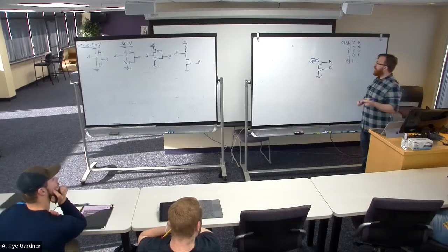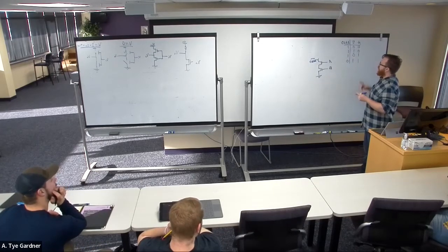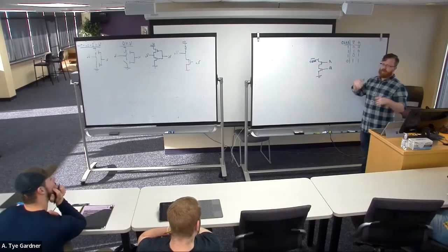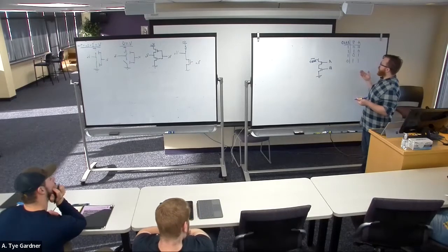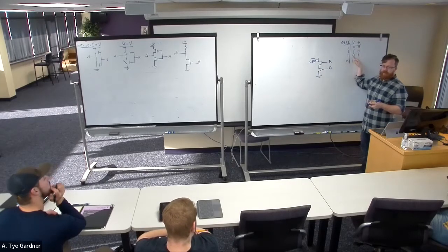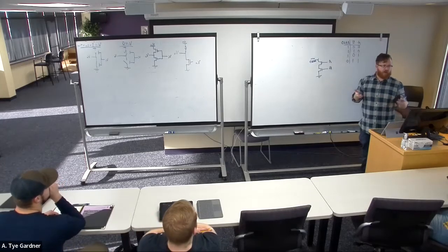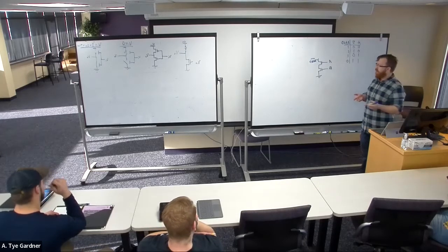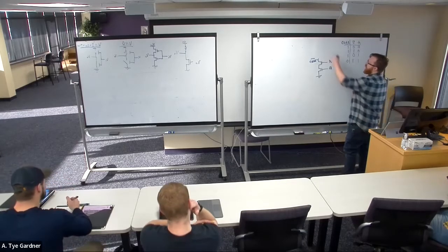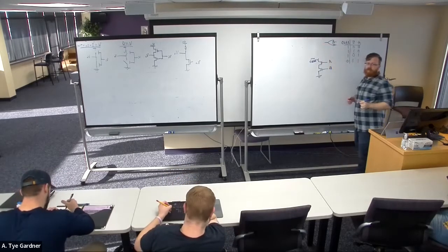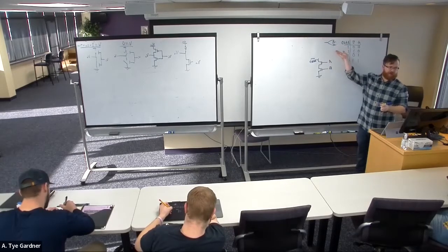Now I need to look at it and say, what happens if, or rather, let's do the other way. How do we make 1s? We want the output to be 1 if we have 0, 0, or 0, 1, or 1, 0. We have this OR situation, and it's ORed from the perspective of the zeros. It helps to think of the NAND gate in this form for this part, where we care about the OR of the zero inputs.